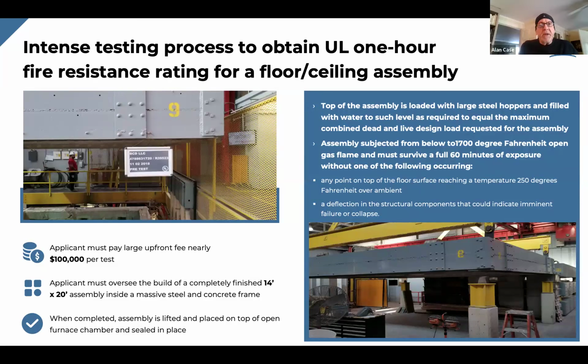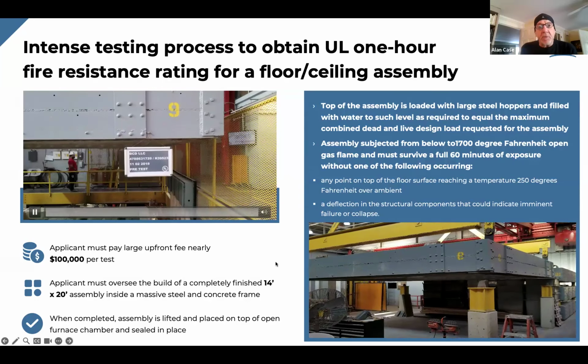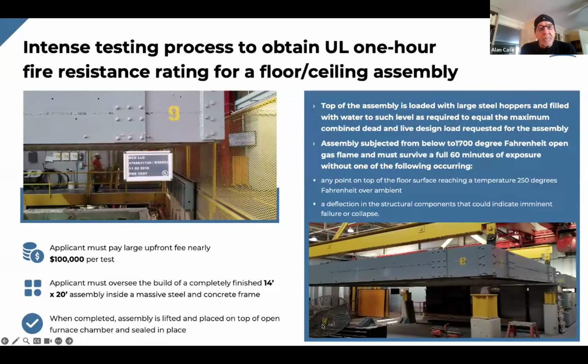Well, once the assembly is built in place, and it's built by the engineers at UL, so it's extremely precise. Every screw is within 1/8 of an inch of where it's specified and so forth. Once it's finished in the frame, then it's lifted with a gantry crane and flown over and set down on top of a furnace, an open top furnace, where the test will actually be conducted. It's sealed in place. The furnaces are filled with thermocouples. The test assembly is filled with thermocouples.